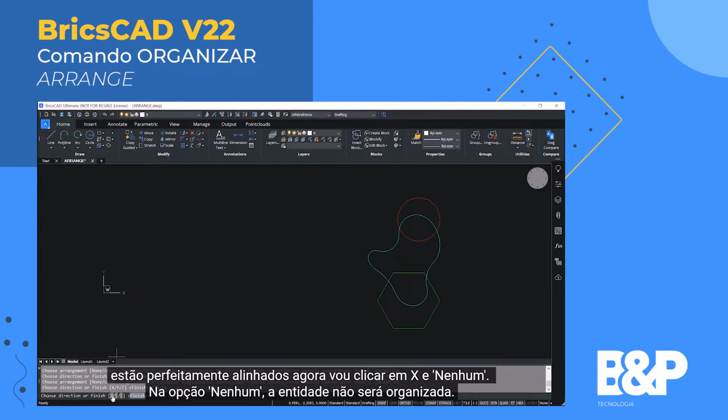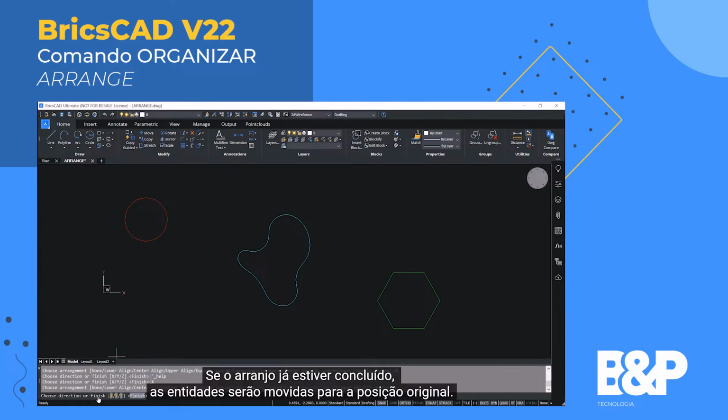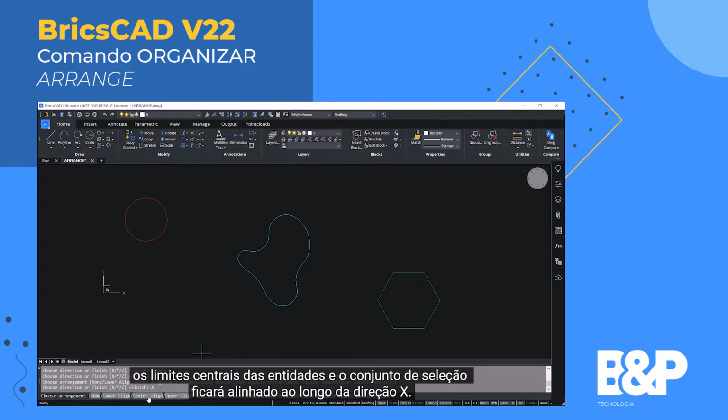Now I'll click on X and none. In none option, the entity will not get arranged. If the arrangement is already done, the entities will be moved to the original position. I'll click on X again, then I'll click on center align. In center align, the center bounds of entities and the selection set will get aligned along the X direction.